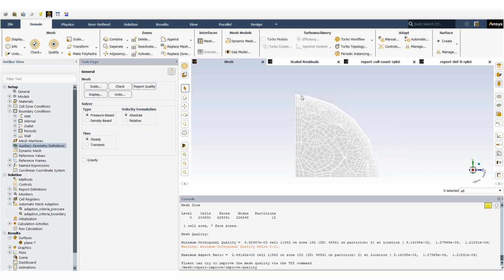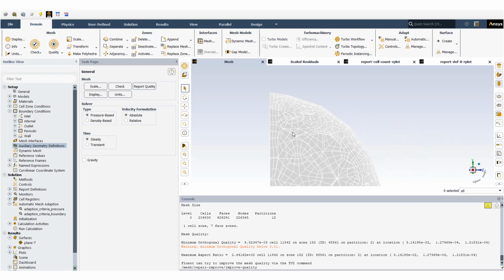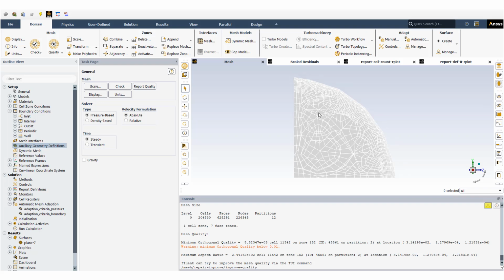This is where I already showed you that I have 6 segments, 1 2 3 4 5 6, at the original mesh, and this one and this one, for example, are initial nodes. So the way the mesh adaptation works is that it just adds more nodes in between the initial nodes, but does not really change or improve the curvature that I needed.